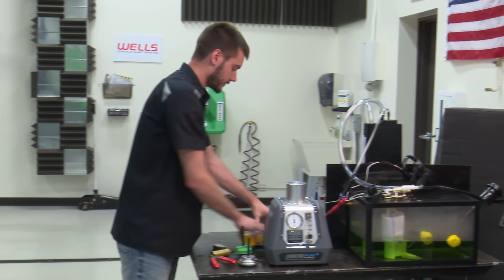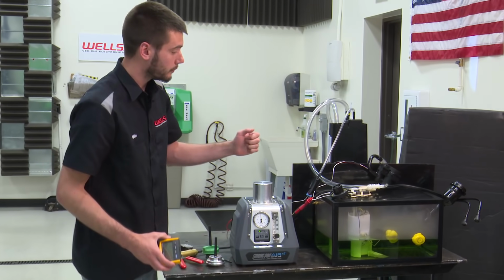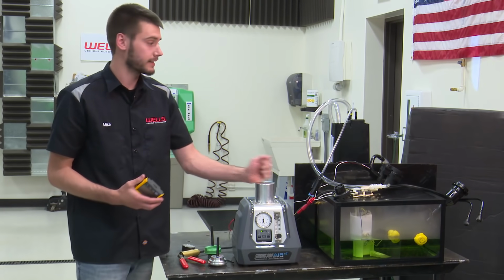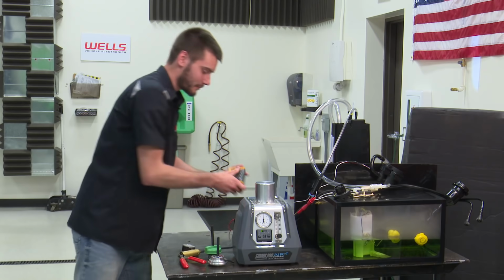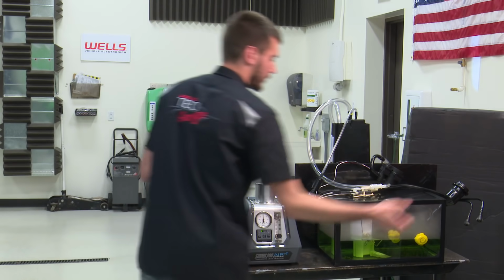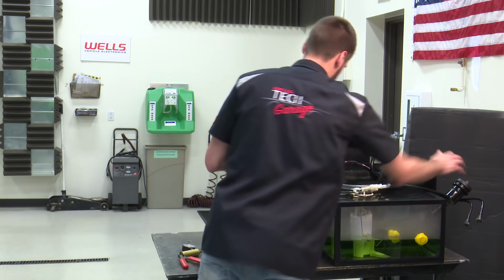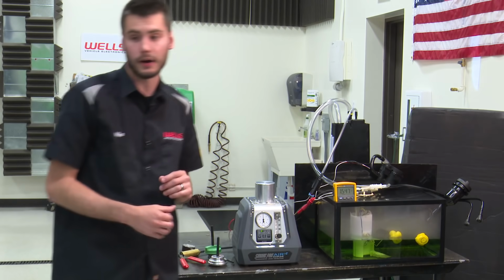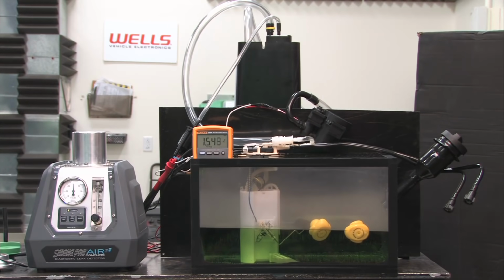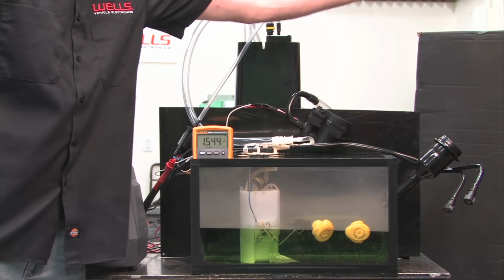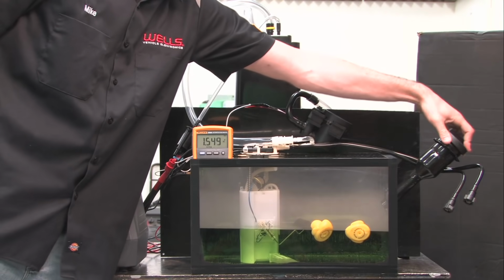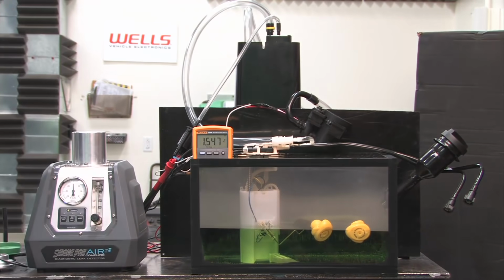Okay, let's go over here now, and I'm going to show you guys with the voltmeter connected to our fuel tank pressure sensor. I'm going to both apply vacuum and pressure to our tank, and we're going to watch as I turn on the voltmeter. We're going to watch this all happen, okay? I'm going to apply our gas cap back to here. Here's our voltage right now. So I think you guys can read that, yeah, we'll call it 1.5 volts at atmospheric pressure, right? Our gas cap is off, there's no pressure, no vacuum inside of our tank. We are currently at atmospheric. We will see this thing sit right about here.